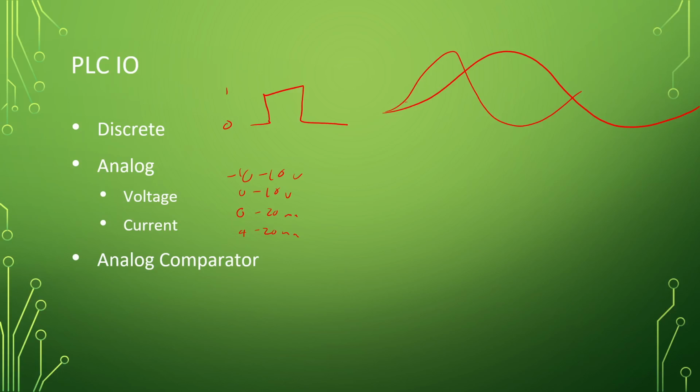Right? That is a little device, and I've tried to find these, and I've failed miserably. So I don't know if I'm using the wrong terminology. I got this right off of our little assembly system over there, because there's one on there for the height sensor. We're actually detecting the height of the discs. It's a little analog comparator, and it's a device like this, and you've got 2 knobs on it. And you run your analog sensor into it at the top, and you've got 3 discrete outputs on the bottom. And what you have here is, this is your low level, this is your high level.